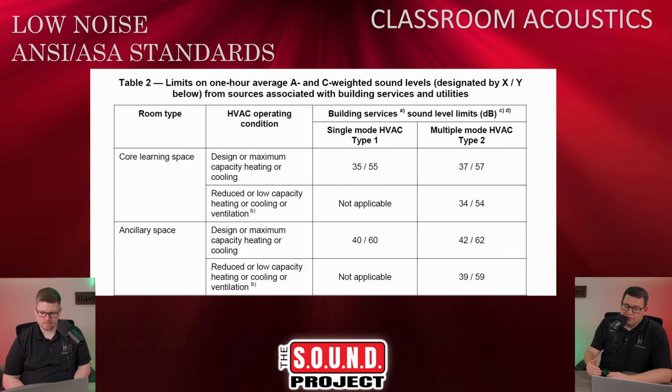With these low noise standards in the ANSI ASA guidelines, for every different type of room, there is a given NC rating or an ambient noise level that you're trying to hit. It's great to have these guidelines as a designer because it gives us requirements to shoot for.